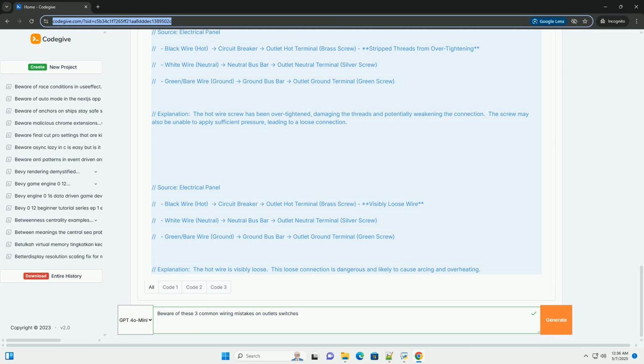Code references, NEC examples. NEC 250.4(A)(5): Electrical equipment and wiring shall be installed in a manner that creates a low impedance ground fault current path to facilitate the operation of the overcurrent device. This emphasizes the importance of a low resistance grounding path. NEC 250.130(C): Equipment grounding conductors shall be sized in accordance with 250.122. This ensures the grounding wire is of adequate size to carry fault current.